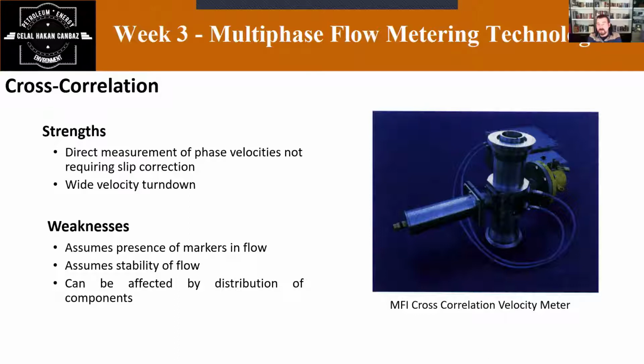For example, you had some condensate banking in your wellbore, heavy components parted in your wellbore, and that heavy components start to move through your multiphase meter. When this meter faces those components, it directly fluctuates.